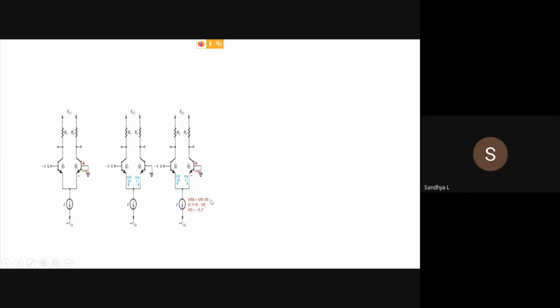VBE is VB minus VE, VBE is 0.7 and VB is 0. So 0 minus VE, so VE is minus 0.7. So here we have minus 0.7. Here we have minus 1.